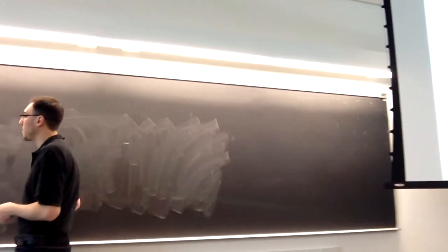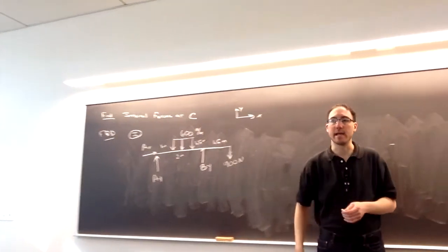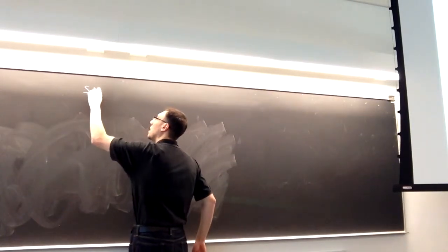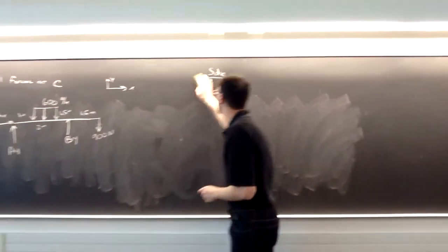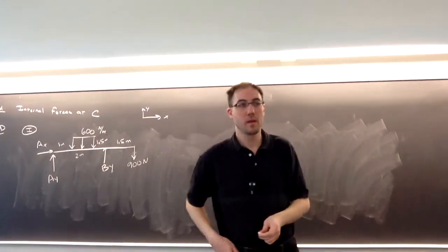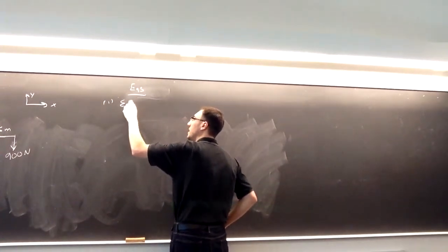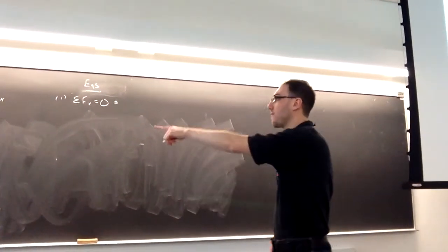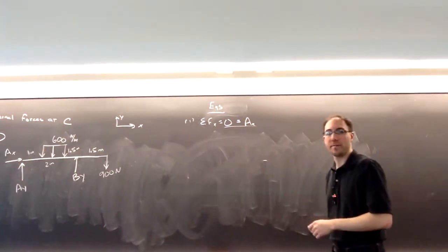So looking at our free body diagram we just made for the external picture, we have AY, AX, BY. We have 3 unknowns. It's a 2D rigid body, so we can get 3 equilibrium equations out of it. Equations are next. From the free body diagram, we can sum forces in the X direction. Because we're in equilibrium, they're going to sum to 0. So based on our free body diagram, the only thing we have in the X direction is AX. So AX is going to be 0.